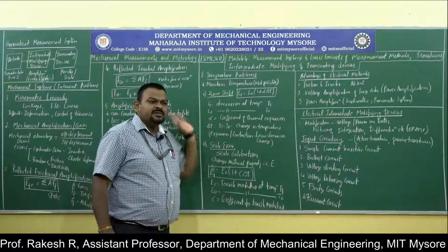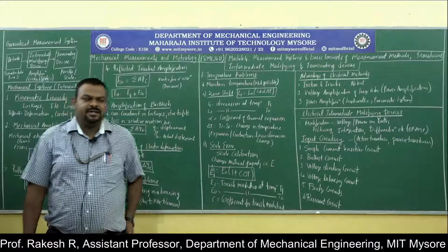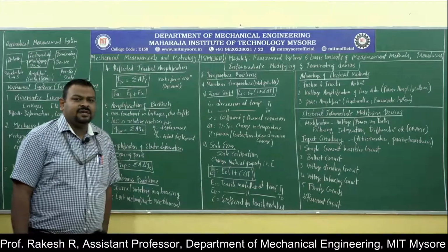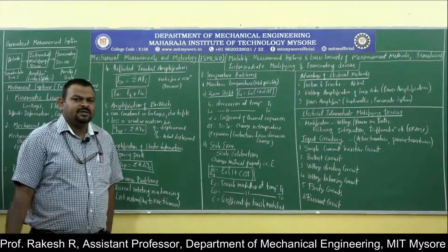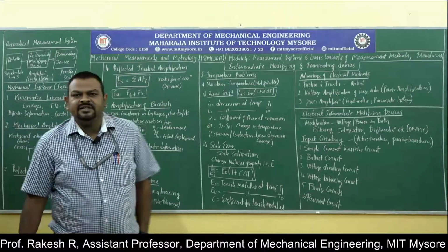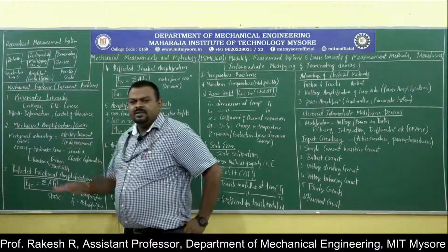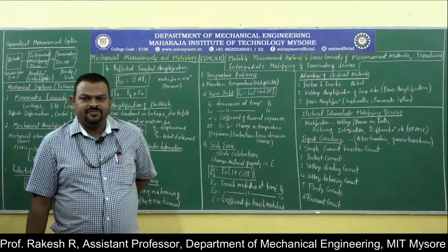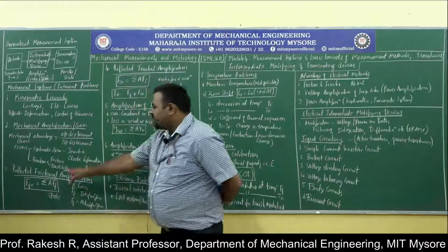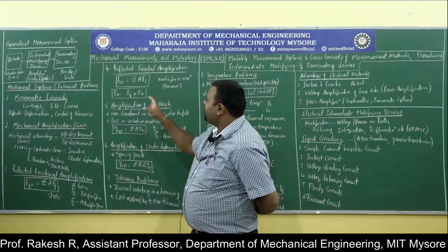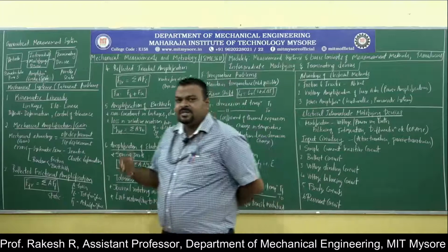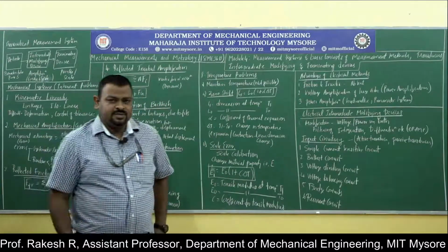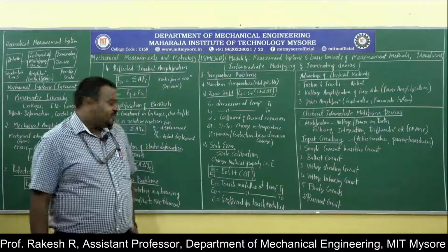Next, there are a lot of disadvantages in the case of mechanical systems, but in most cases, when it comes to cost, it is economical. These errors will always be there, but we need to avoid the amplification of errors. That's why the names reflected frictional amplification, reflected inertial amplification. That means we will be calculating what is the total inertia force, what is the total frictional force, what is the total backlash,